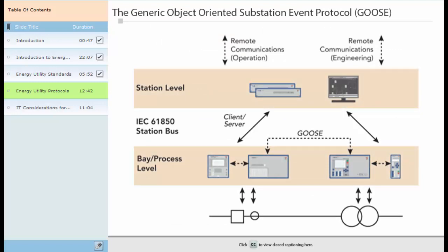These services not only include regular commands of control, reading and writing, but they also offer a new and wide range of services for grouping data objects, reporting and logging, as well as sending fast messages such as GOOSE and GSSE. The GOOSE protocol, specified in IEC 61850, is intended for distributing event data throughout the whole substation network.